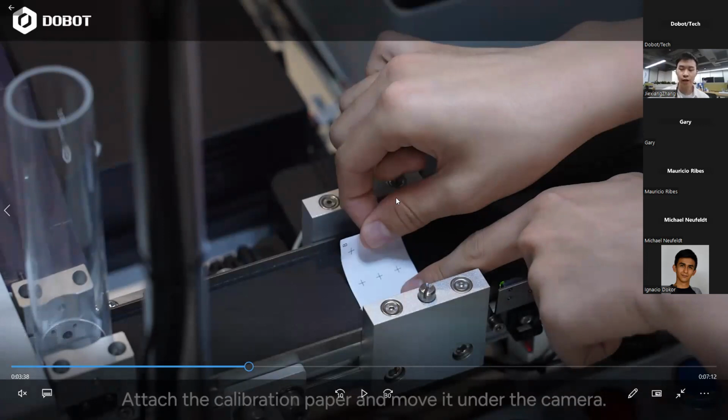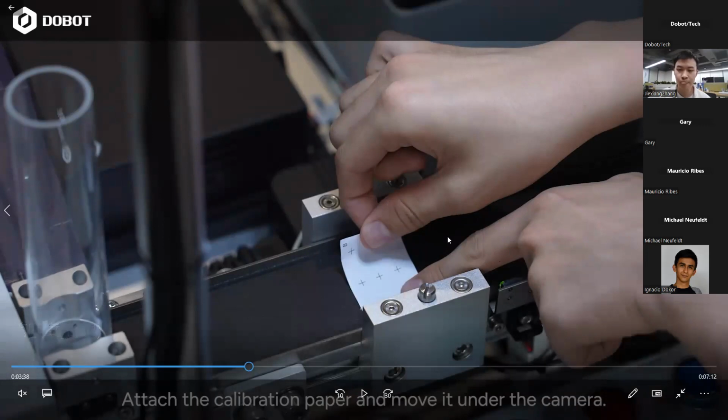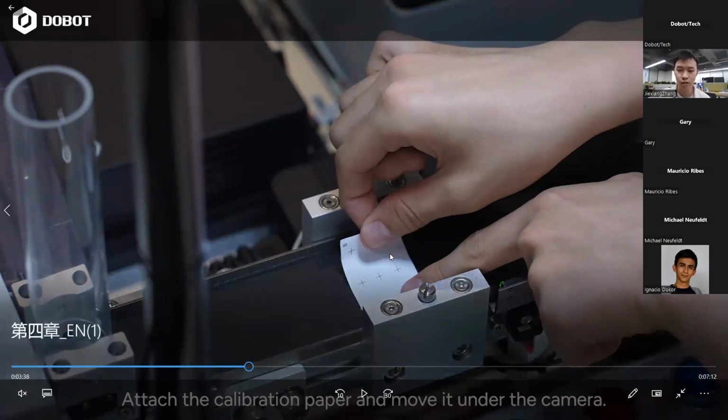Because we are combining the vision system, we also need the calibration paper to combine the pixel coordinates of the camera and the coordinate system of the robot, so that we can match them and the robot will know the exact coordinates of the image.